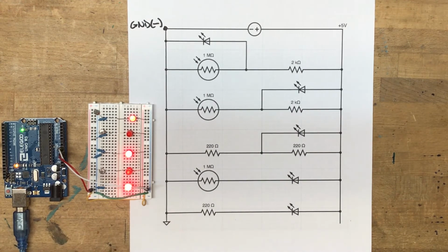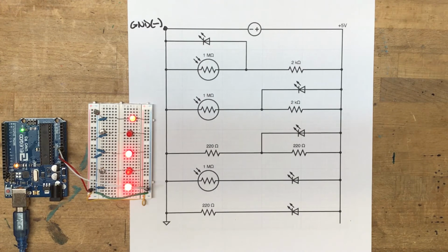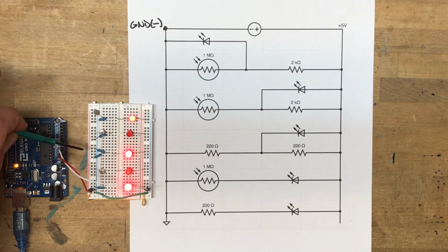Now the second one up is the light dependent resistor, which can vary from 500 ohms to 1 million ohms depending on the light. So if there's less light, like if I cover it with my finger, it'll go dimmer, and if there's more light, like a little flashlight, it'll get brighter. So we can use that to some advantage, but the next 3 circuits above that are all voltage dividers. The first one, third one up here, is 2 220 ohm resistors creating a voltage divider.